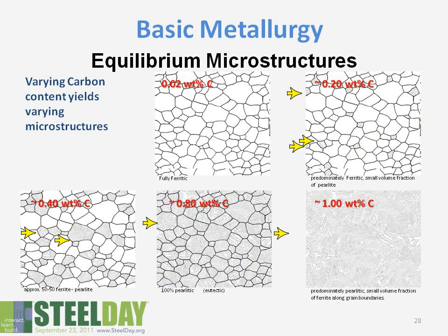Above that, if you compare these two slides here, 0.8% versus greater than 1% carbon, we actually see the dark grain boundaries disappear because we have the additional ferrite now precipitating out at the grain boundaries, and as a result, we can actually start losing some strength.